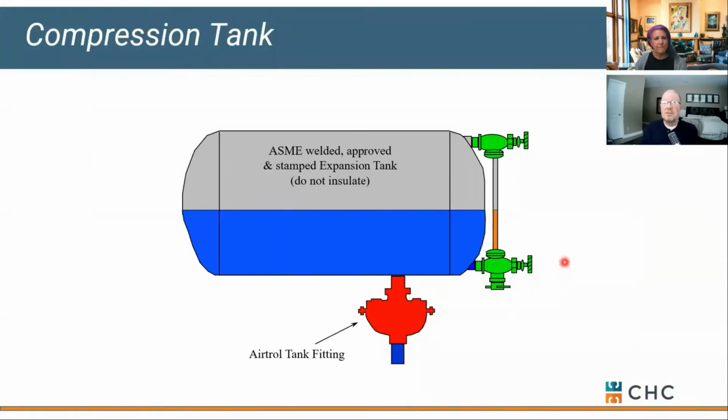Now, a compression tank, you still see a few of these out there. They typically don't get tied in with new design, new projects, but existing buildings, you can still run across these. And picture these as just a big piece of pipe working on a balance of air and water. As we add more water, we're compressing the air. When our boiler cools down, that compressed air forces this water back out into the system.